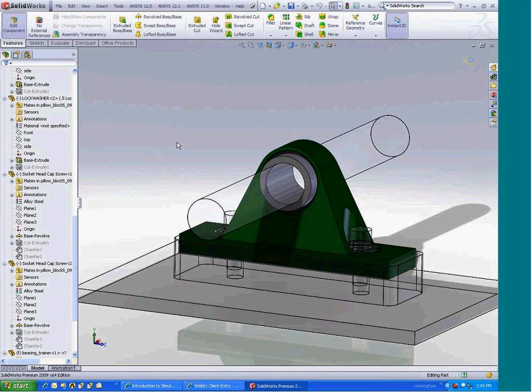As I mentioned before, we can always do our defeaturing operations inside the CAD tool. Defeaturing would be things like removing details in the geometry that don't play a significant role in the analysis portion. Those would be things like chamfers or fillets in areas where we're not concerned about stress. We can do that in SolidWorks, but again, it requires that we modify our parent CAD file.